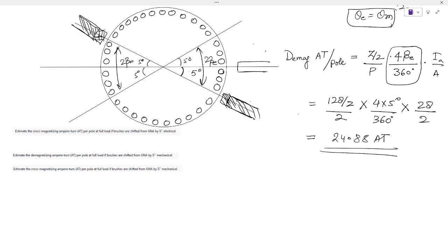The conductors under a good concentration of field will have higher EMF induced, and the field distribution across the periphery of the armature will be disturbed. So all the conductors will not have uniform EMF induced. When the brushes are commutating, there is a possibility that some rotational EMF is still available in the conductors undergoing commutation due to the non-uniformity of the magnetic field.